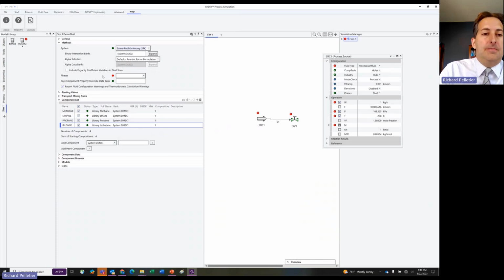All right. Now, the last section that we need to cover here is the phase designation. There's a pull down here, and you see it's marked as red, where we have to pick what phases to consider when using this fluid. And this is important because you're trying to gauge and kind of balance your level of accuracy in terms of the results that you get out of the software with the performance out of the software as well.